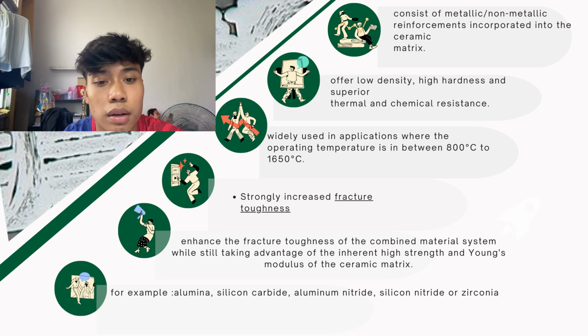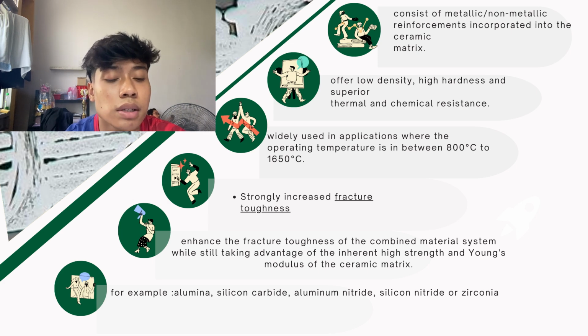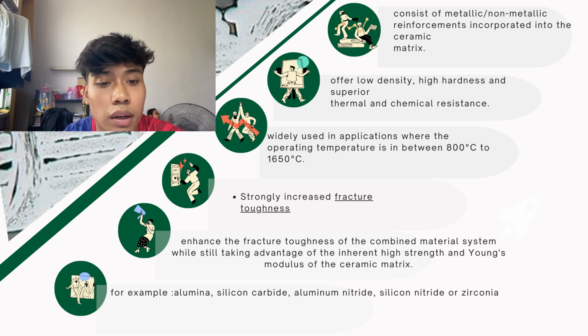CMC is widely used in applications where the operating temperature is between 800 Celsius and 1650. CMC strongly increases the fracture toughness. CMC also enhances the fracture toughness of the combined material system while still taking advantage of the inherent high strength and Young's modulus of the ceramic material.